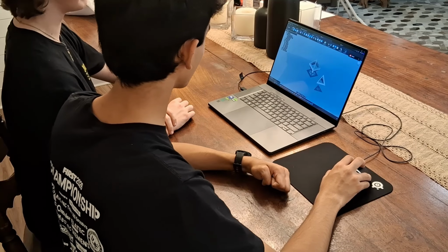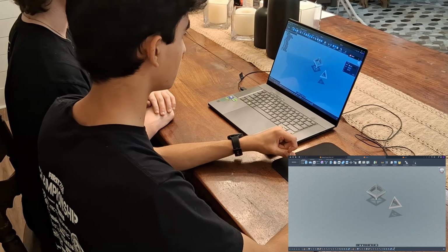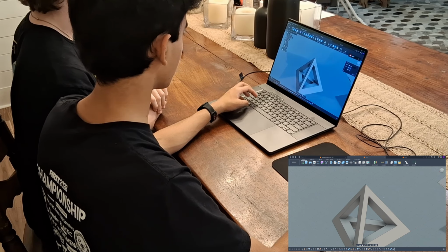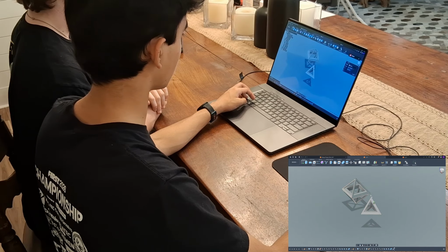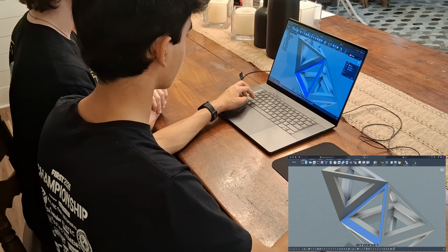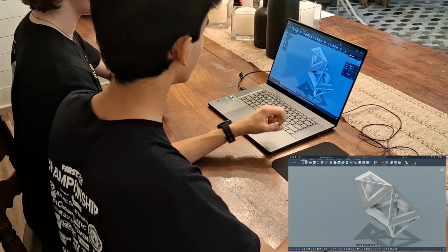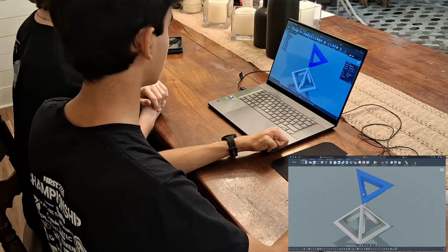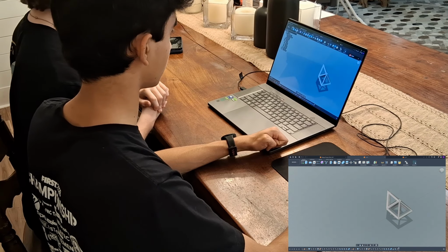Okay. Alright, so now our fun part. So we're going to use our align tool and then get a bunch of these little 3-sided base pyramids and put those on the faces of this new shape we made. So what we're going to do is select this corner piece right here with our align tool, and then we're going to come over to the matching side on the new pyramid thing, and then we're going to select that corner right there. So it doesn't look right yet, but what we're going to do is use our rotate tool and our move command. Select that, select our axis, and then now all you have to do is rotate that down until it matches. So that's their angle, 110 degrees. So do you want to try that?